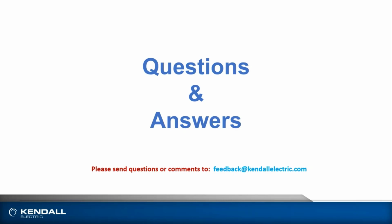Thanks, Rob. Is aliasing allowed in CCW programming? Brian, that's a question I'll throw your way. I don't know the answer to that one. Here's what I do know: you can alias your local IO that comes in to a different name. I don't know if you can alias an internal tag to another tag. That's what I'm not real sure about. But from a local IO standpoint, you can.